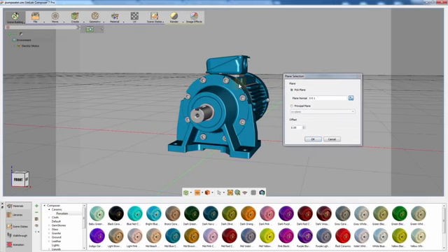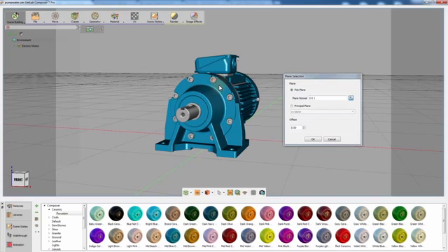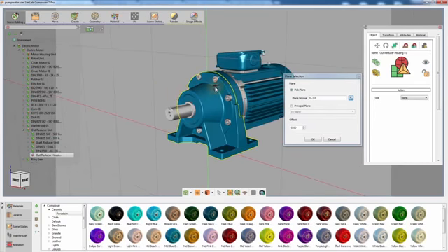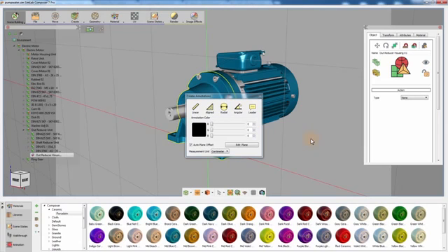Click on a parallel face and notice that a blue arrow has been created in the place of picking, displaying the normal of the plane you selected. Notice also that the grid has been rotated to match the plane you selected for annotation creation. Aside from picking a plane from the 3D area, you can determine the plane by selecting one of the principal planes in SimLab Composer. You also have the option to offset the plane you have selected parallel to its axis. Click OK to set the plane and initiate the Annotations Creation dialog window.